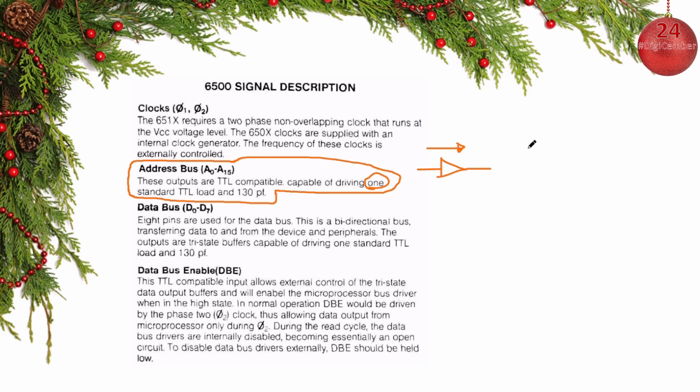And that you have to do in the C64 and other systems where you have other devices or DMA that can control the address bus. But on our system and most one CPU systems without DMA, you don't have more than one device that controls the address bus, and that is the CPU.